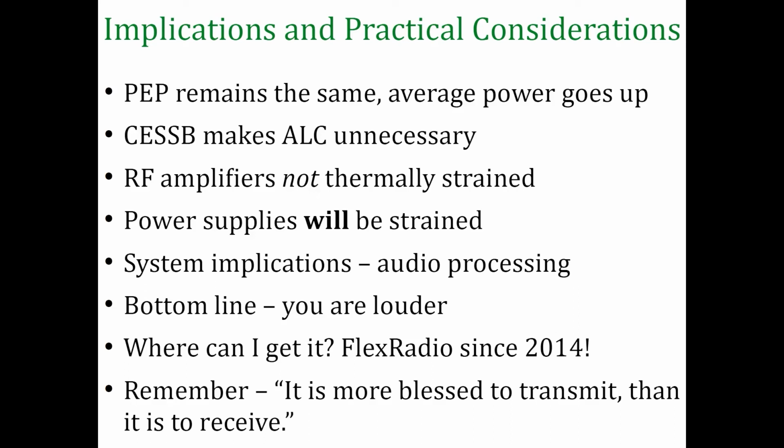Current sideband technology doesn't do very much baseband audio processing because conventional sideband overshoots like crazy. So today's sideband radios rely on ALC and sometimes RF clipping. As we have shown, these techniques really are not very effective. But with CESSB, the audio processing can be and should be moved backwards into the baseband audio domain.